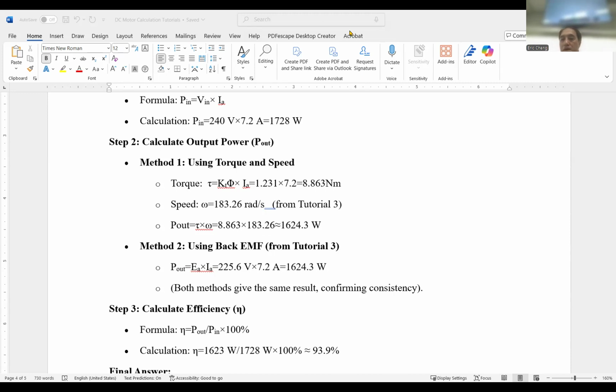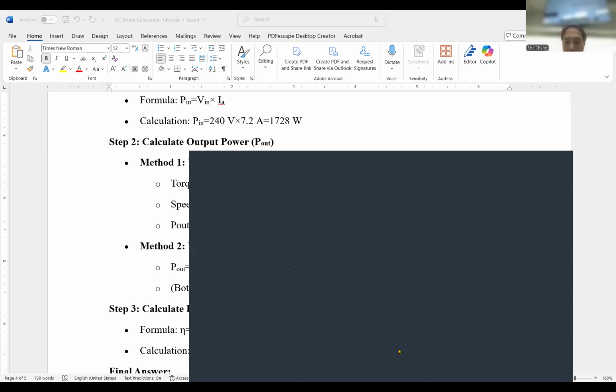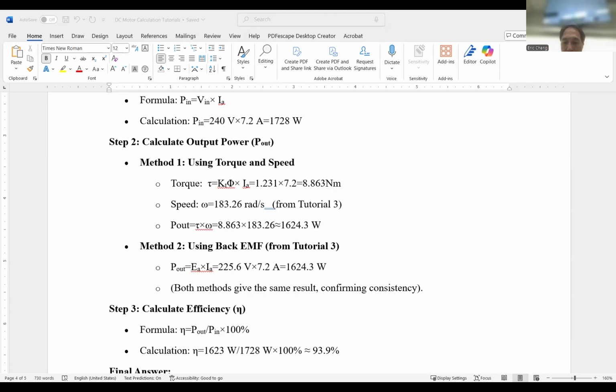The last few slides there. So this is the formula, right? The ripple current comes from the voltage equation, from the L dI/dt equation. So the voltage minus back EMF minus the voltage drop on the resistor, divided by LA, will give you the ripple current.